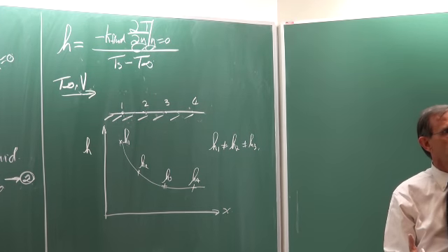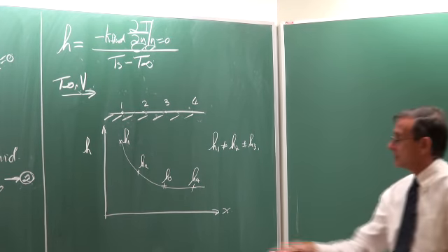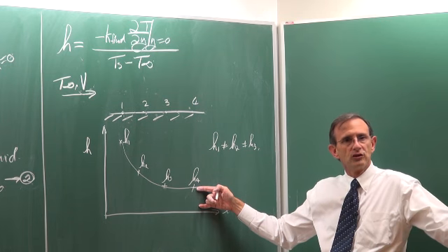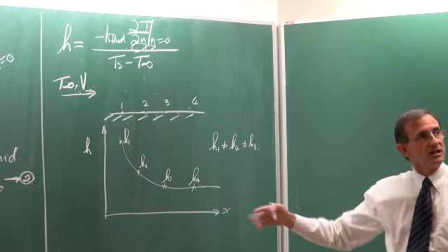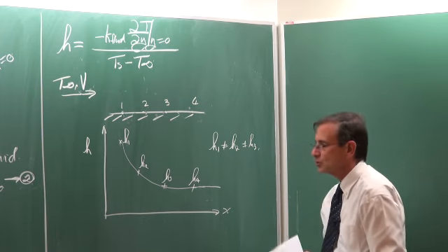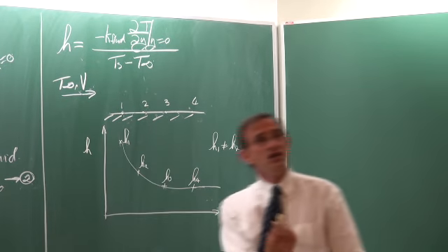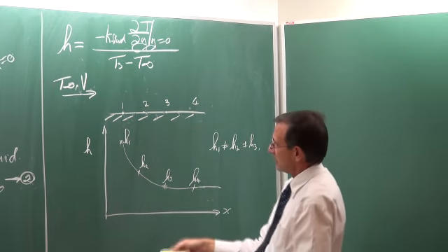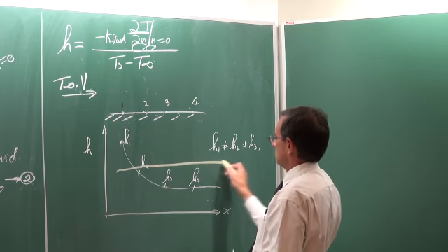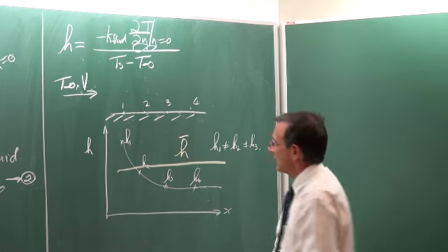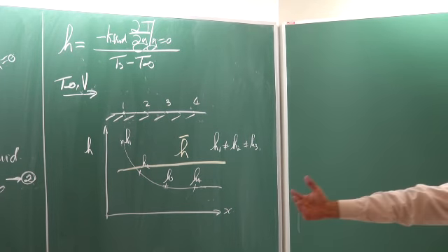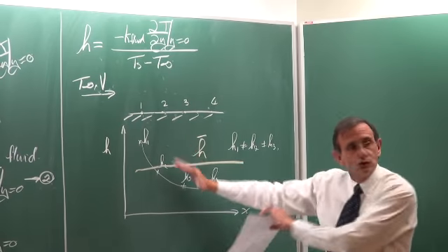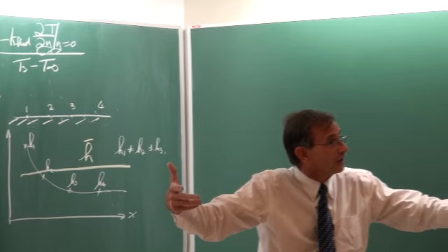So in general, the heat transfer coefficients are not the same. At a stage, they will get to the point where the flow is so-called fully developed, and we will get to that later on, and then they will be the same. But in general, the heat transfer coefficients will not be the same. So as engineers, if we are interested in a specific body and we do have data like that, we're going to look at it and say that is sort of the average, and we would like the average heat transfer coefficient. In many cases, we would like the average. But to get the average, obviously, we need to understand what is happening on the inside of it.